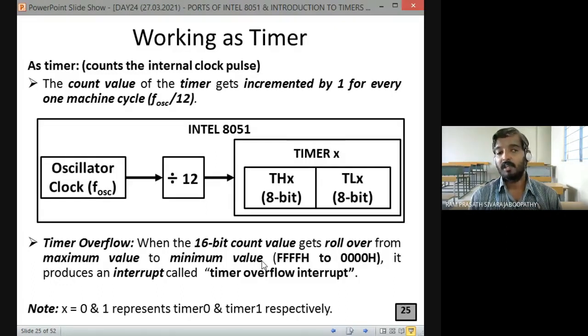Can you people tell me one answer? If I put the count value as 50 in the timer bar counter register, after 50 cycles, is it going to interrupt the microcontroller? Imagine and tell me. We will stop the session here; time is almost 11. Is my question clear? If I put the count value as 50 in that timer bar counter register, is it going to generate 50 microseconds?